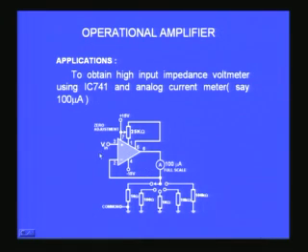It is a very good electronic voltmeter because the input impedance is very high and the output impedance is also very high in this feedback network, and therefore I just connect a normal current meter, panel meter, which are not very expensive, and op amps are also not very expensive. You can combine them with a few resistors and build your own very high resistance electronic voltmeter.